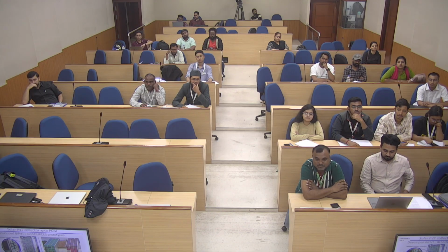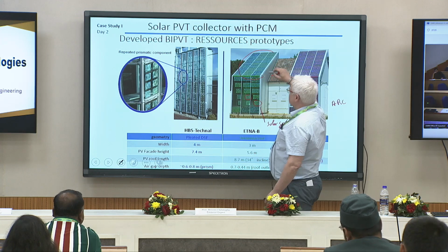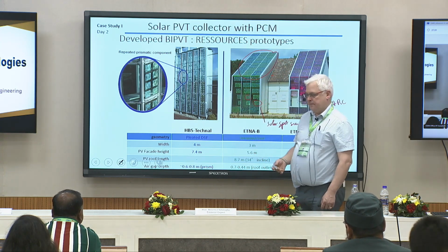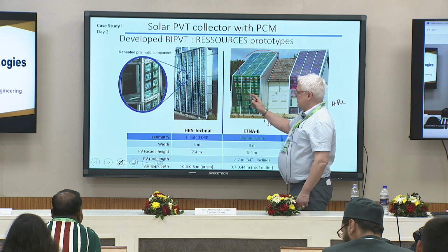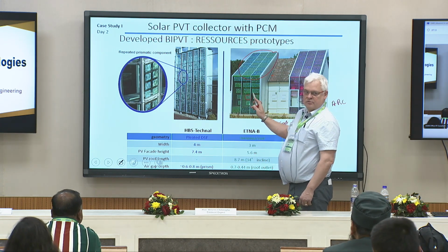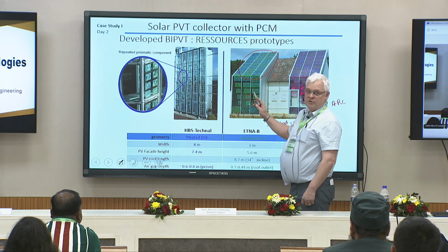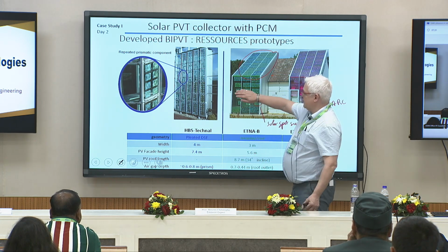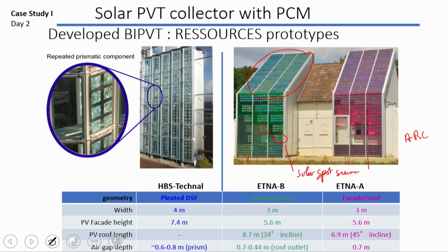So you can have one inverter for that, okay? Seems to be uniform, opaque, and so on. But for this, it's a kind of mismatch, because each module has a different power, okay? So it looks like some modules are in shadow, because there is no cell, okay? So for this, you are obliged to put one microinverter per panel, okay?